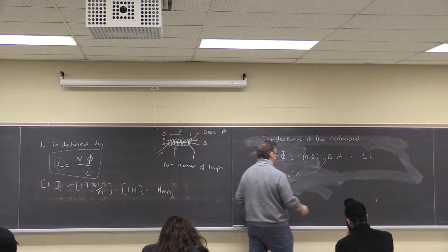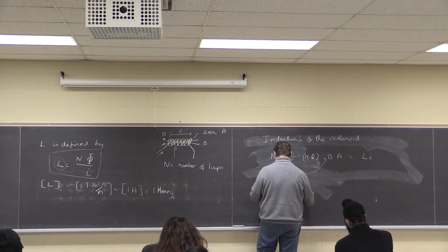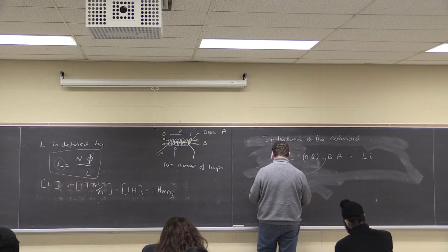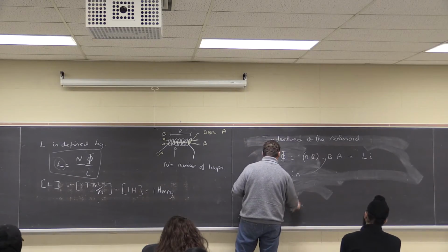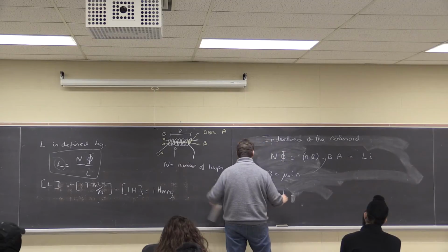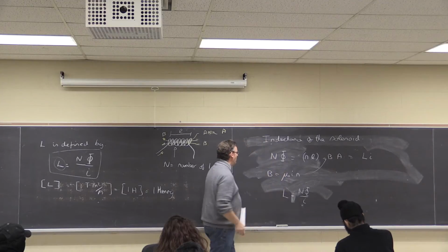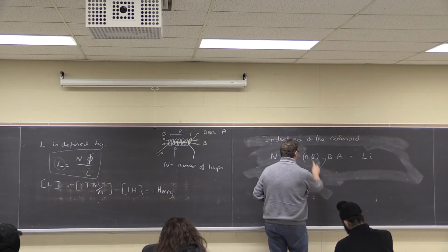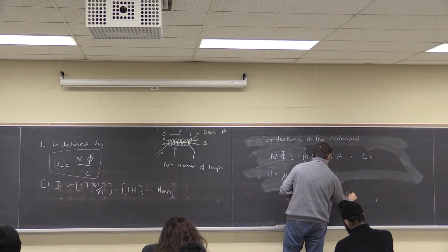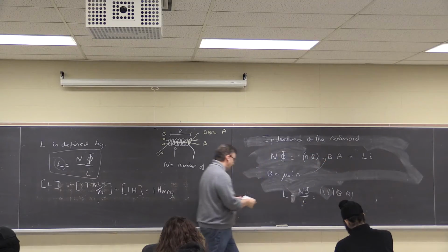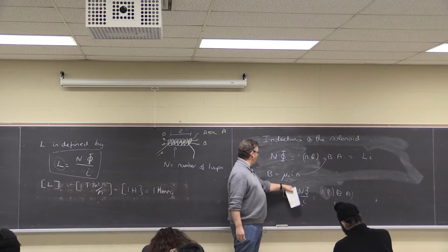And that would tell us what? That would tell us the inductance times the current is going to be... no, I'm just going to say the inductance is this equation. It's N phi over the current. This is my N phi up here, so that's N small l B times A divided by the current. Okay, so I've just plugged in for this.